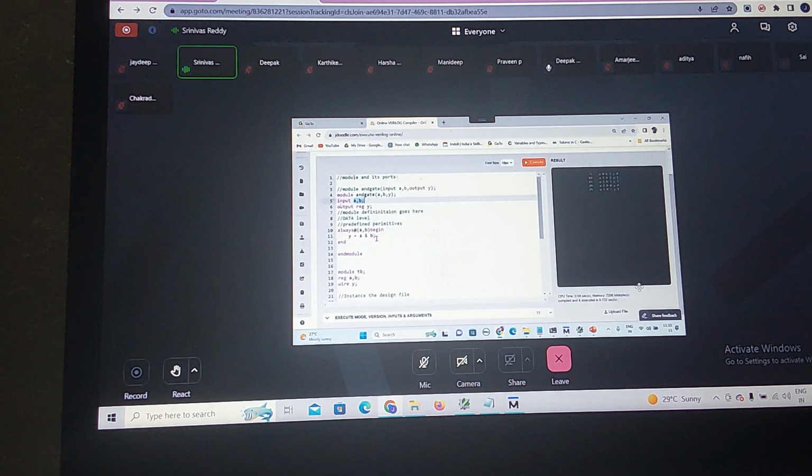So when you are working with the behavioral model, the output will be declared as reg data type. Y has to do this AND operation, and that should be stored in a register. So inside your always block, whatever LHS variables you are using should be reg data type.